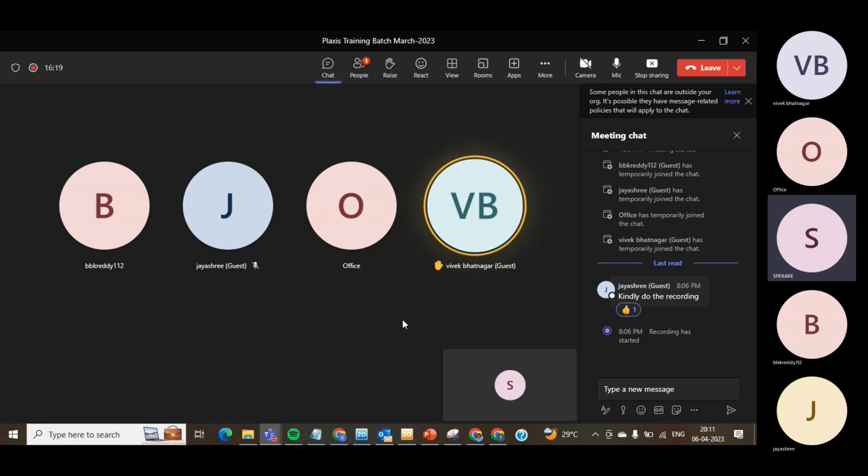If your material properties are not changing, you can freeze that and change only that particular property. But if you would like to change your material properties also, there is a feasibility that you can do that. Do I have to assign material properties again for 6 noded elements? No, not required. If you are changing only the value, it is not required.